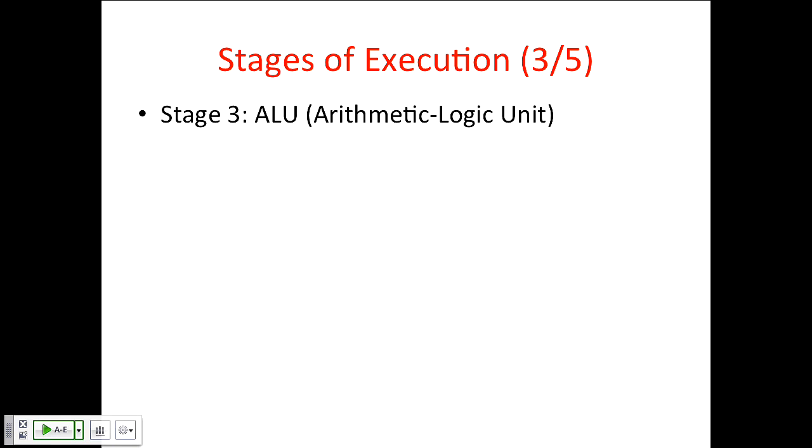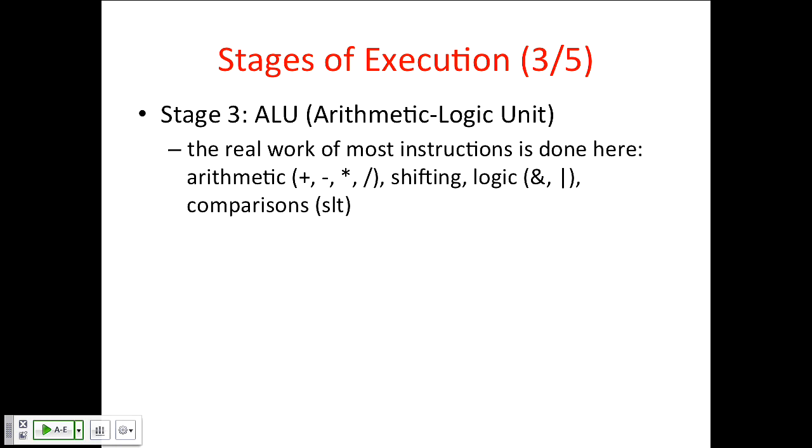So now we've gone through instruction fetch, getting the bits from memory, and instruction decode, figuring out what the instruction is going to do, and reading any register values it needs. Now we move into execution, where we actually start doing some work. And in there we'll have the arithmetic and logic unit. So, things like add, subtract, this is where the adder circuitry will live in this stage. So you fetch the operands, you've got the 2 register values, you feed those as inputs to the adder. The adder works away and produces the value you need as a result of the addition. And similarly for shifts, logic, comparisons, and so on, right? That's where the ALU lives.